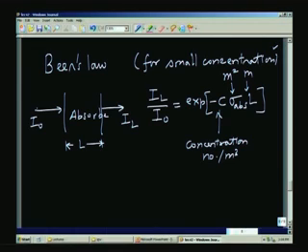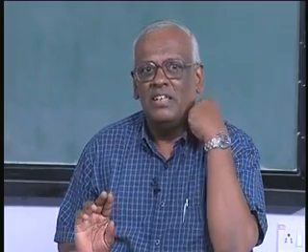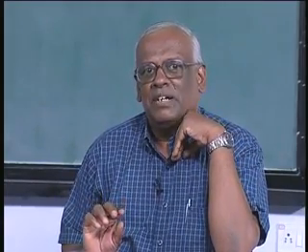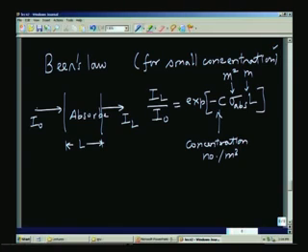So, differential absorption means that there is a difference in the absorption capability of the particular gas, because these two wavelengths have this particular property. One wavelength is absorbed, the other one is not. So, let us look at what is going to happen to the light which is passing through the medium. L is the thickness or the extent of the medium.